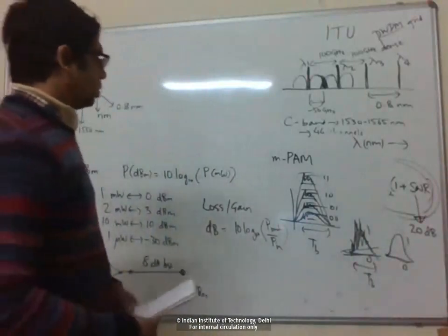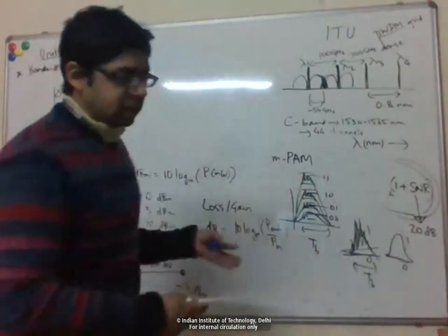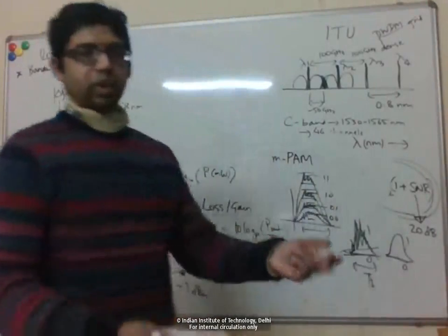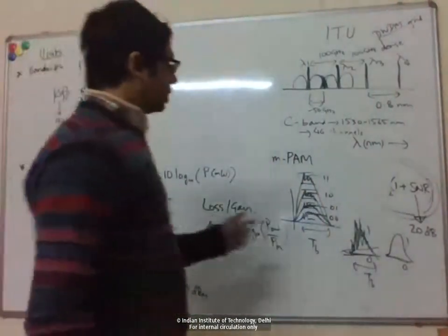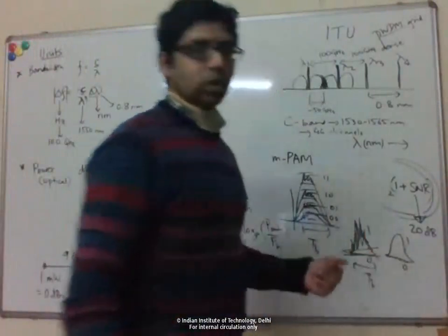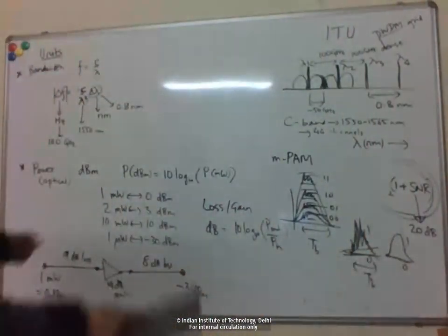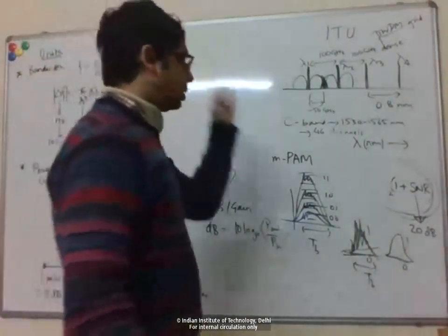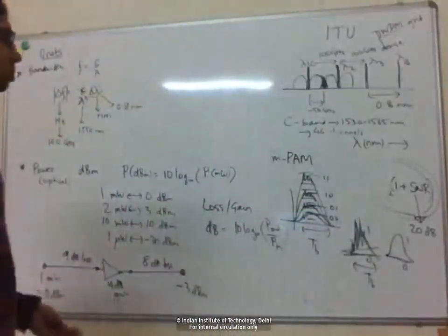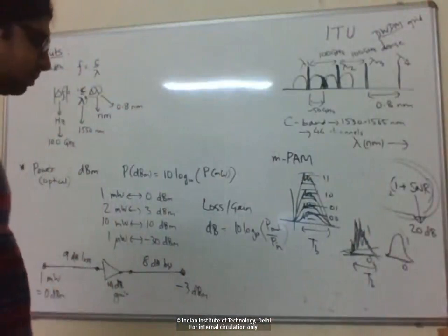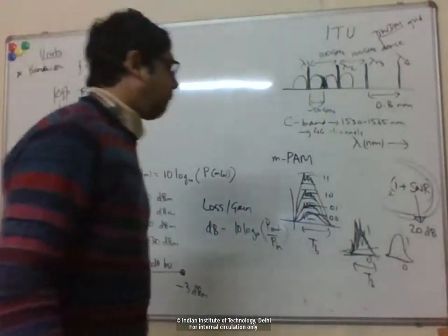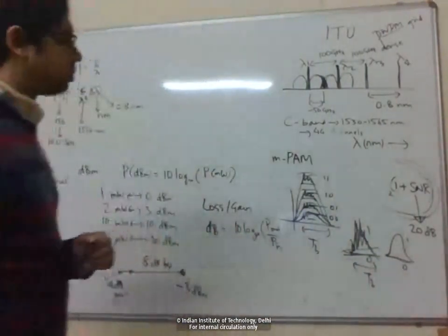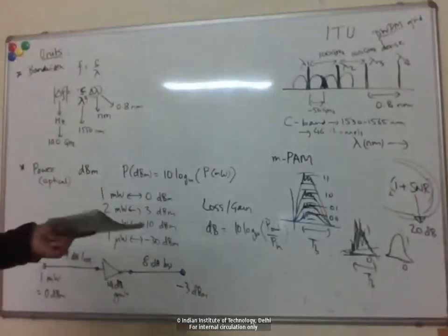Whatever you do, you have to make transmitters which encode your electronic data onto the optical format, and then at the receiver you have to decode it. So there's a trade-off. On-off keying is the simplest thing you can do. Because all the other properties we discussed of the optical communication system are so much better than electronic systems, even with on-off keying people are able to get very good performance. Only if you want to push to the limits do you go for higher modulation formats. Anyway, I hope that's clear.